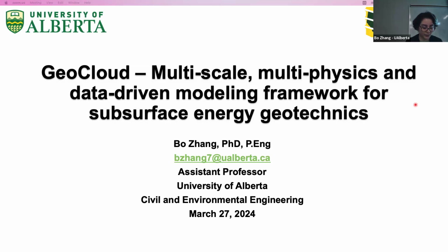Dr. Zhang's talk will focus on a multiscale, multiphysics, and data-driven modeling framework for subsurface energy geotechnics. The multiscale component is a development of elastic and plastic numerical upscaling techniques and extending them using machine learning techniques for improved computational efficiencies. The multiphysics component is the implementation of upscaling techniques to coupled thermal hydromechanical simulations.